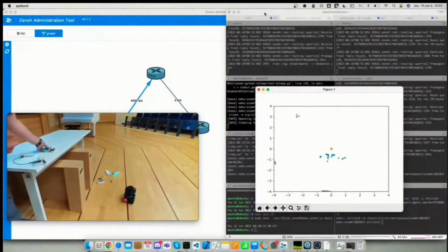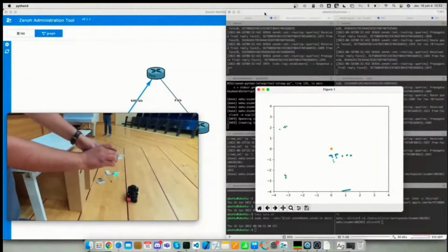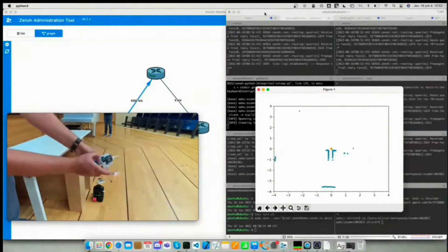So that we can integrate and do the sensor fusion of all these sensors that we have in the factory, integrate them with the control of other operational processes that we also have in the factory, and be able to have finer control of what happens. So in this case, whenever something is too close, we block the operation of the robot. If the sensor is green, meaning that there is no object in the range, the robot can move freely. So if we see it now, it's far away from the fence, so we can move it again. If you go close again, yeah, the sensor turns red and it stops.